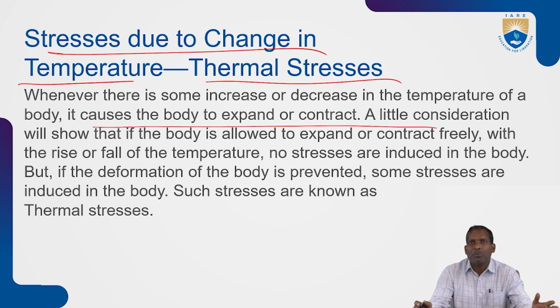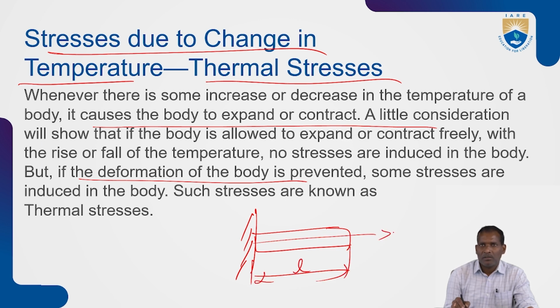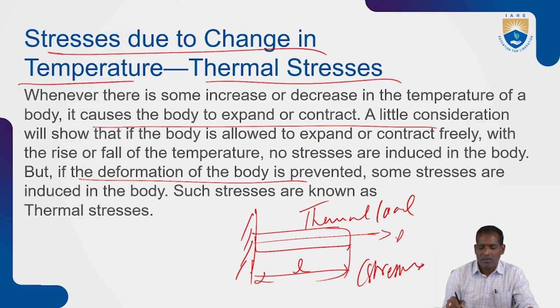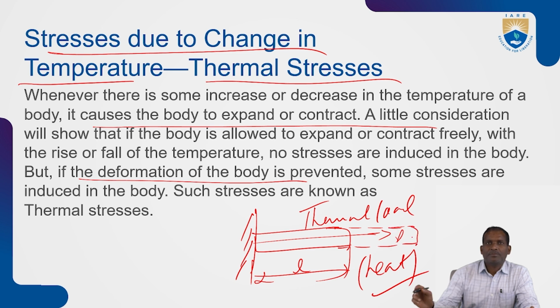But if the deformation of the body is prevented, suppose the body has length L, and you subject it to load and also give thermal load, and you keep on increasing the heat, the stresses will keep on increasing like this. If the deformation of the body is prevented, some stresses are induced in the body. Such stresses are called thermal stresses.